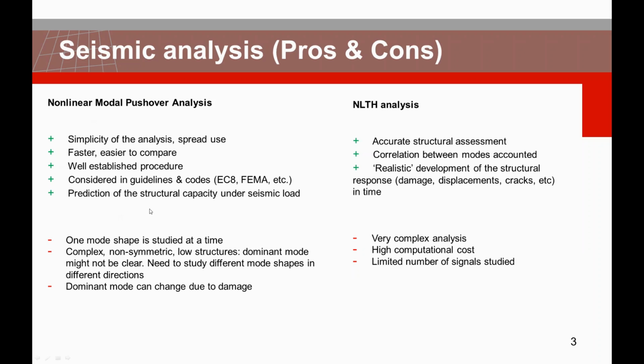The main advantage of the nonlinear pushover analysis is the simplicity, and that's why it is widely used. It is faster and easier to compare, and it is a well-established procedure. That is why it is considered in guidelines and codes for the prediction of the structural capacity under seismic loading. However, the disadvantages are that only one mode shape is studied at a time.